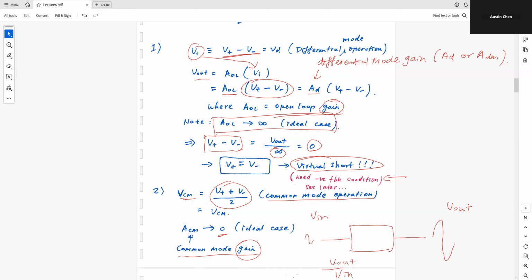So this is my gain, by definition. My voltage gain is equal to V out over V in. So I take the ratio of this signal divided by the V in. The ratio between the two, V out over V in, is my gain. And in this case, you expect to see signal amplification.